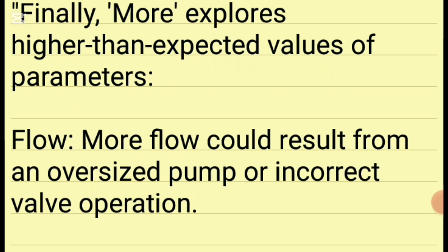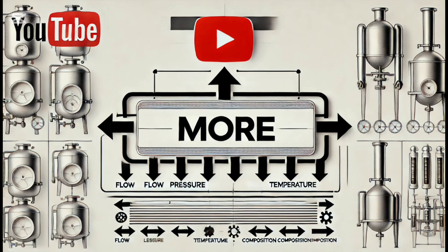Next guide word is more. Finally, more explores a higher than expected value of the parameter, meaning higher than the design value of the parameters. Parameters are flow, pressure, temperature, level and composition.